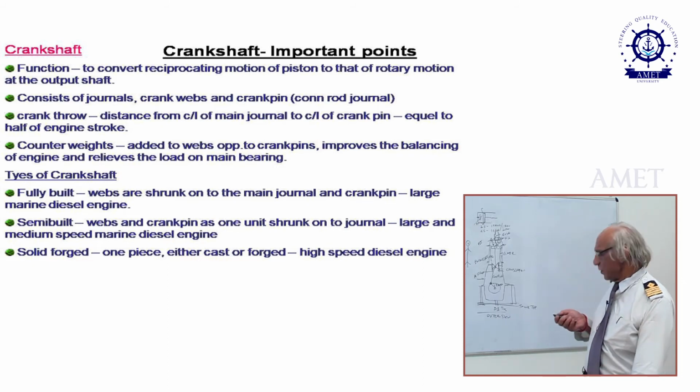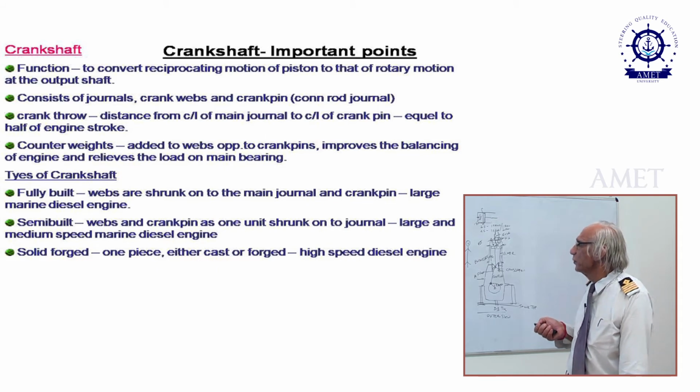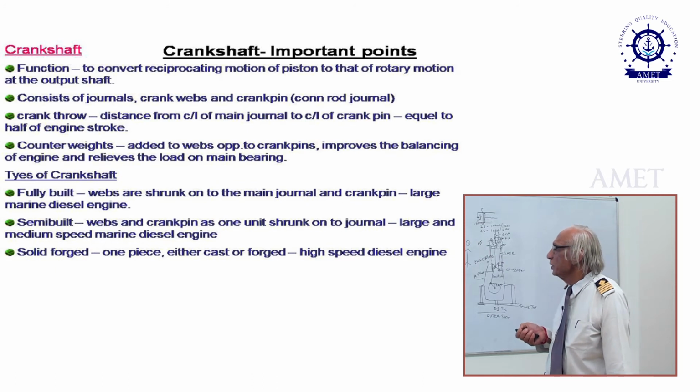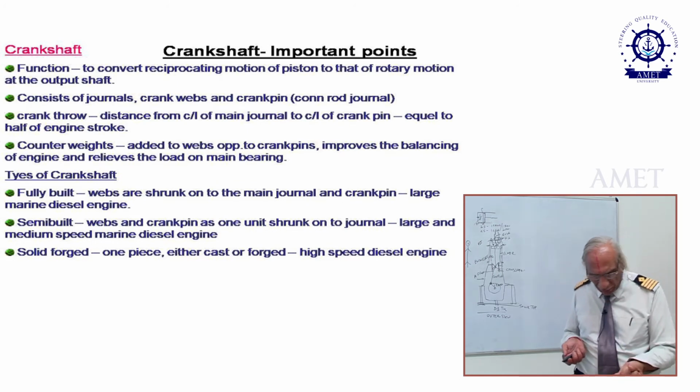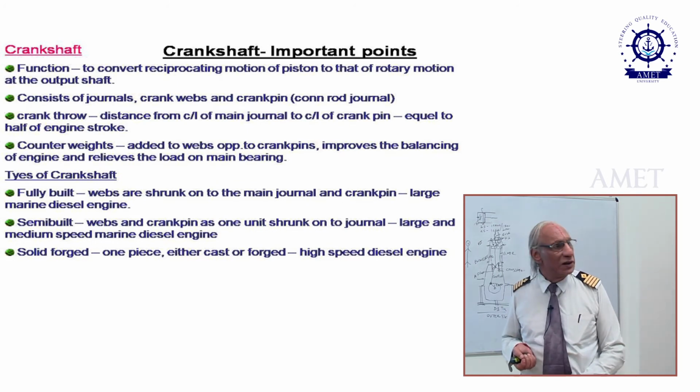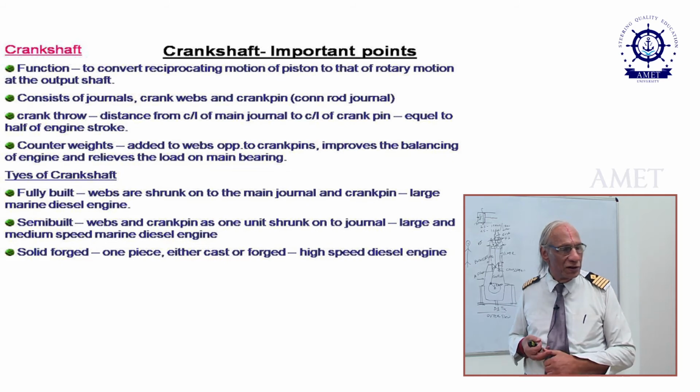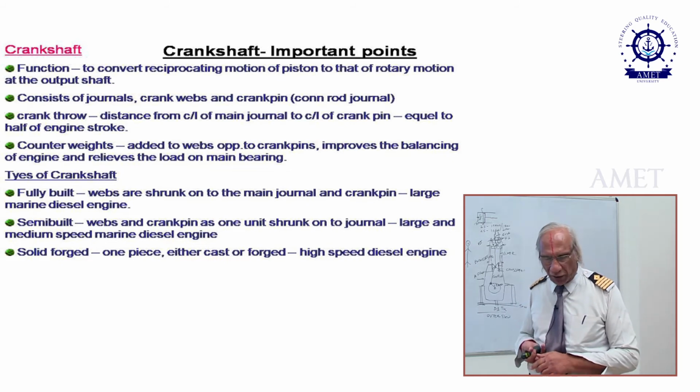Counterweights are added to the web opposite the crankpin, which improves the balancing of the engine and relieves the load on the main bearing. Now, this is the main function, mainly to transform the linear motion of the piston, the reciprocating motion, into a rotary motion.